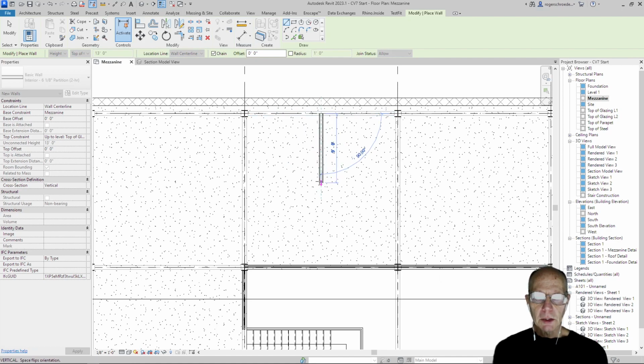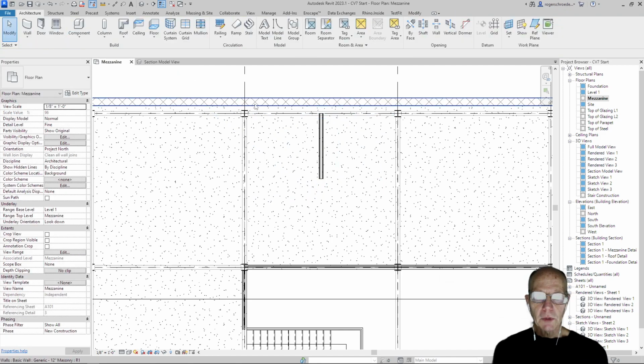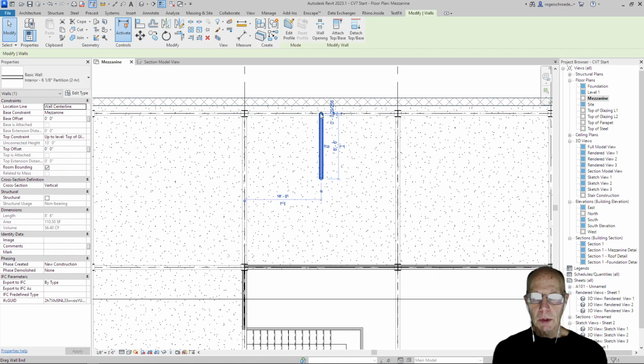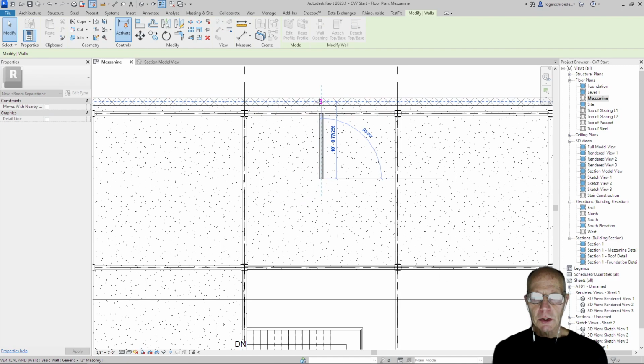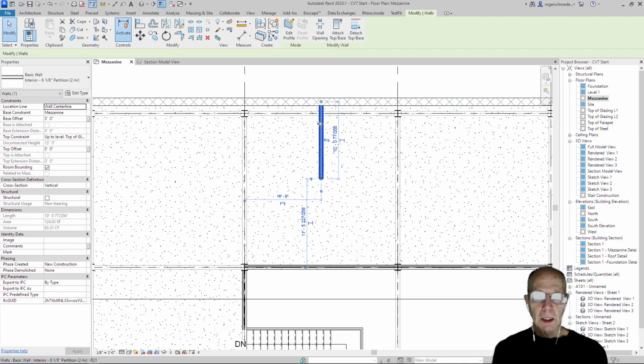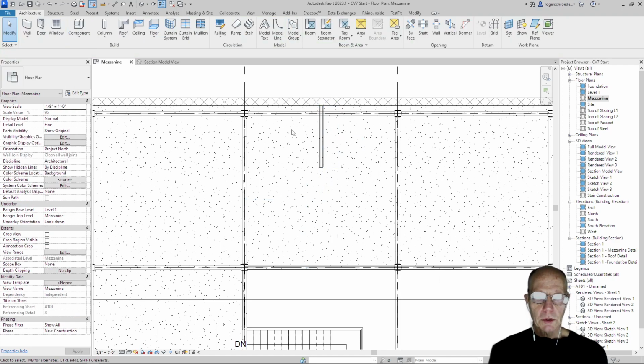And I'll come out and we'll just make this random for now, because I've attached it to the beam, and I really want to pull it back and attach it to that wall. And let's say we want this thing to be 8 foot 6 inches. I want it to be 8 foot, but I'm going to add 6 inches because that wall is 12 inches thick. And let me make sure I put a 6 in. All right, so we have now our center wall constructed.